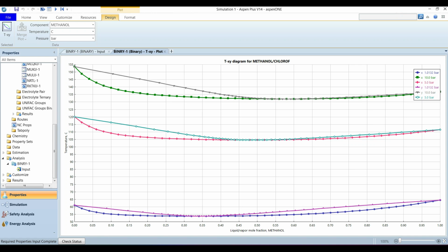But this is not the only thing. At the same time, if we are reducing the pressure, we can favorably enter into the two-phase region crossing the azeotropic composition. But if we operate the second column at a lower pressure, will the second column design or geometry be the same as when it is operated at a higher pressure? There are lots of other variables. How many stages should there be? What should be the reflux ratio or the boil-up ratio in the reboiler? Those are other variables. So this is a very general scheme.